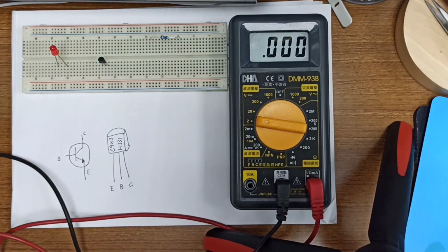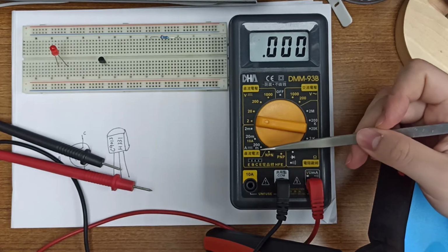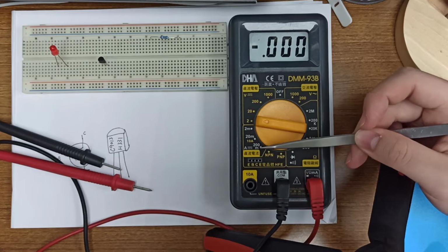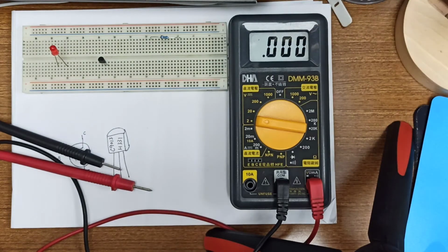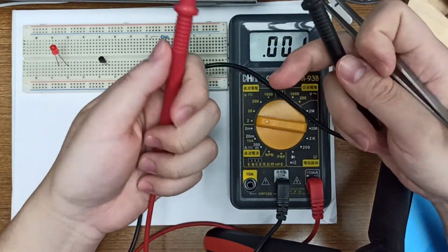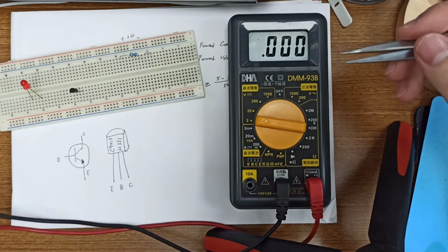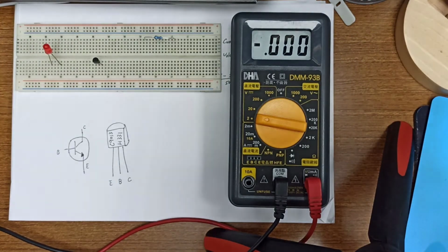Okay. So next, I will now teach you how to use the current function. If you want to measure current, it's very complex, since the current is in a series circuit, we need to cut off the line and plug in the positive red probe and the black probe in the circuit. It is very complex, so we usually don't measure the current using the multimeter. We use another special current probe to measure.